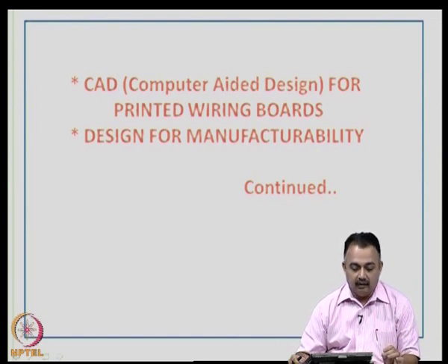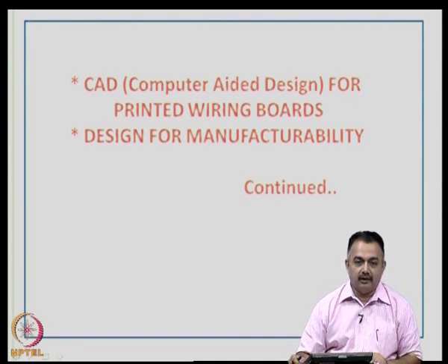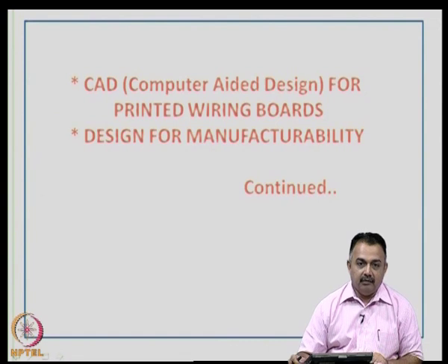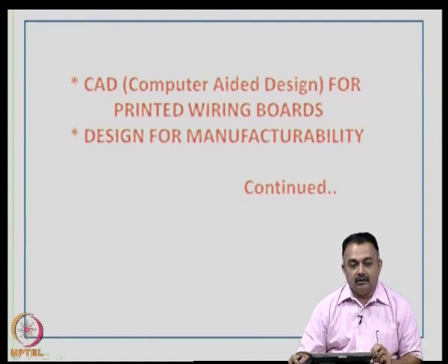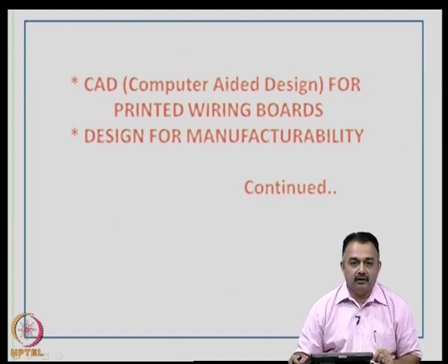It is much more than that, because today CAD not only defines the size of the product, the size of the printed wiring board in some sense, as we saw in the last class, defines the size of the product, the density of the product. CAD also plays a major role in package electrical design and package thermal design. So, once you do the basic interconnections of components, you are going to do a lot of simulation, both electrical and thermal, to make the product more reliable. That is why I said towards the end of this chapter, we will also discuss some key points on design for reliability.